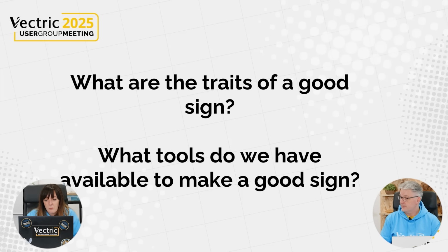Maybe what I'm trying to do is make sure that these lines are quite parallel, and they are. And then I want to make sure that the overall size of this isn't any bigger than 1.5 inches. So I want to put 1.5. This is the diameter all around it, and press enter. And that should be great. So if I hover over that, now it says that outer radius is 1.5 inches. So that's perfect.